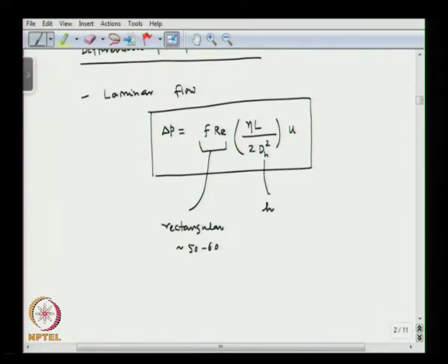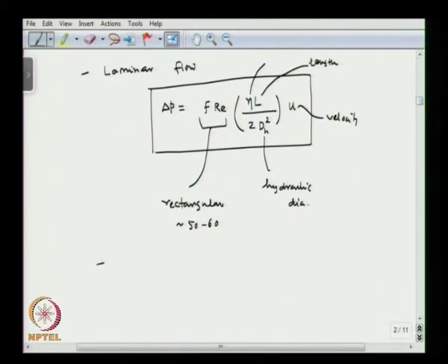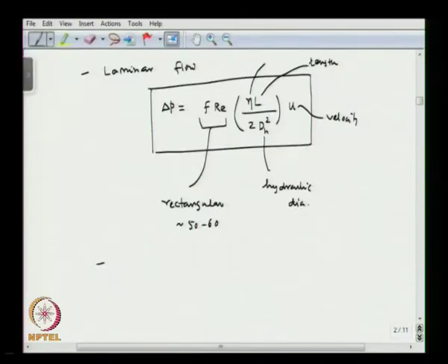And this is the hydraulic diameter, and this is viscosity, this is the length scale, this is the length of the channel, and this is velocity, okay. So, what we see here is that the pressure drop is linearly dependent on flow velocity or the flow rate, okay. So, that is used to develop differential flow sensors, okay. So, we actually measure the pressure drop, and from measuring the pressure drop we predict the flow rate, okay.